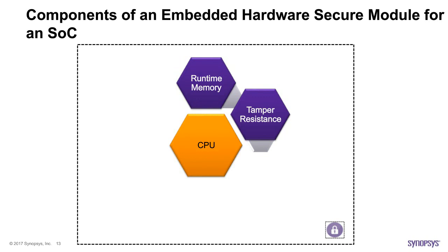Cryptographic accelerators are the next block. Although most cryptographic functions can be supported in software, it typically requires more memory and runs slower compared to using hardware accelerators. With hardware cryptographic accelerators, the CPU can run at a slower clock speed and potentially reduce the overall runtime memory requirements without sacrificing performance.